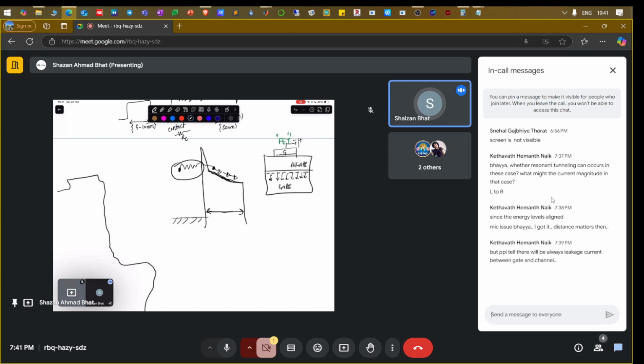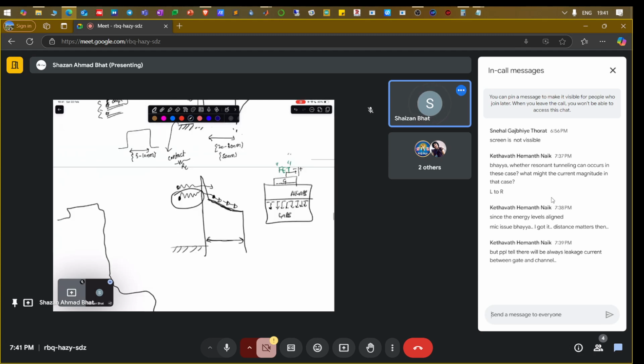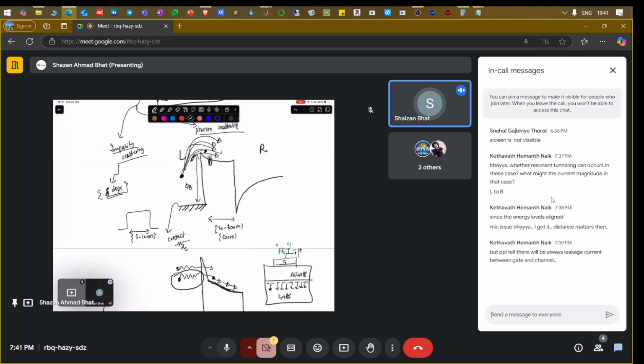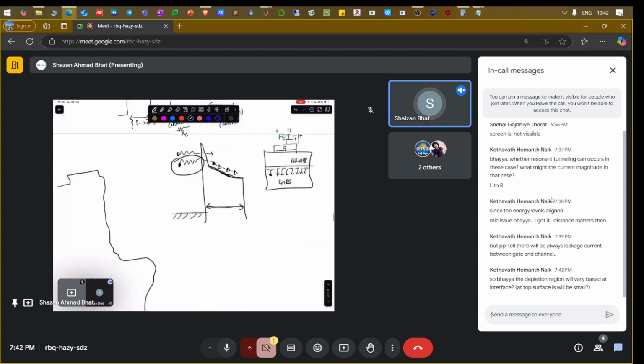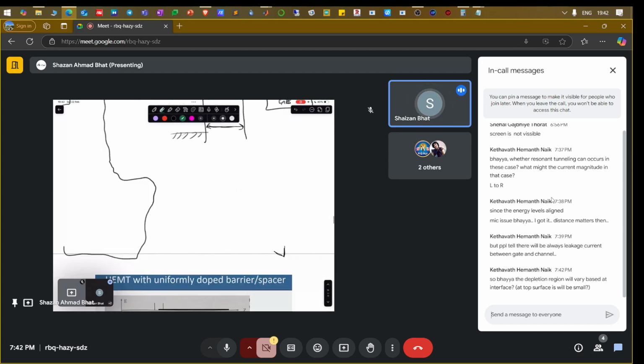But sometimes the leakage can happen, in terms of this tunneling. If this tunneling can happen, or let's say the electron gained much energy and went above the barrier as a thermionic emission, then that electron may come here, it will go down, then it will result in the flow of current in this direction, opposite to that of the electron motion, which is bad. That is the leakage current you are talking about. Otherwise, the current should only flow between the source and drain terminal, which are present in a device like this.